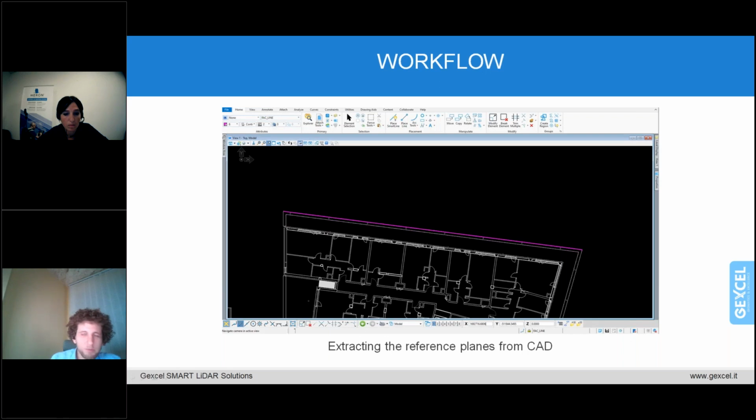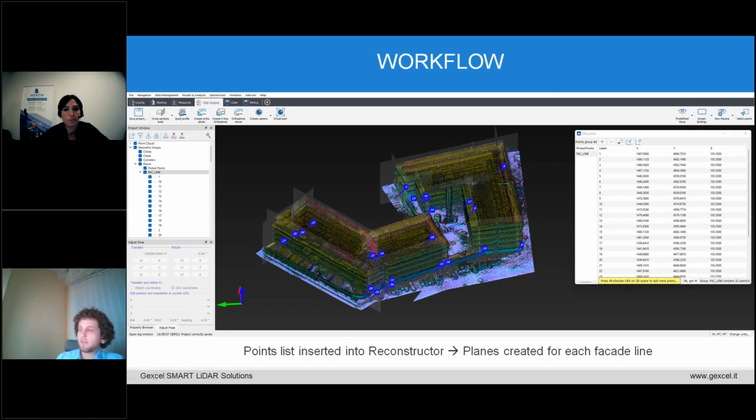So what I would really like to point out again, and I really like that, just by picking the two endpoints of these floor plans, these are within absolute coordinates, so georeferenced, positioned properly within the Hungarian national grid. Just by using, please jump to the next, Georgia. Just by using these floor slab endpoints, we could construct so-called planes and alignments in Reconstructor that we could use as a comparison basis between the plan and the as-built states.